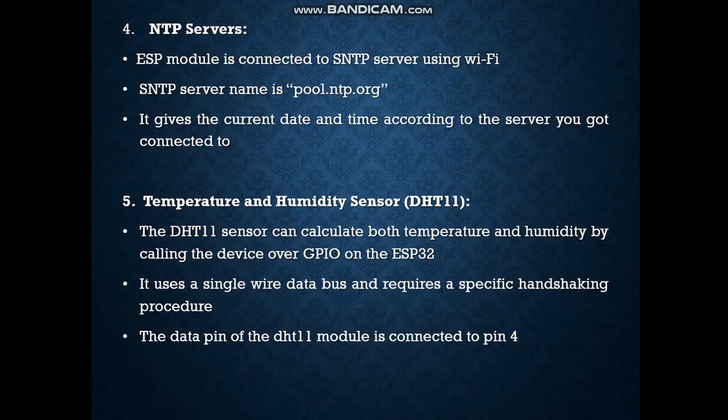Now we'll look at the NTP server. SNTP stands for Simple Network Time Protocol. Its operating mode is set using sntp_setoperatingmode, and the ESP module is connected to the SNTP server using Wi-Fi, and the server name is pool.ntp.org. It gives the current date and time according to the server you got connected to.